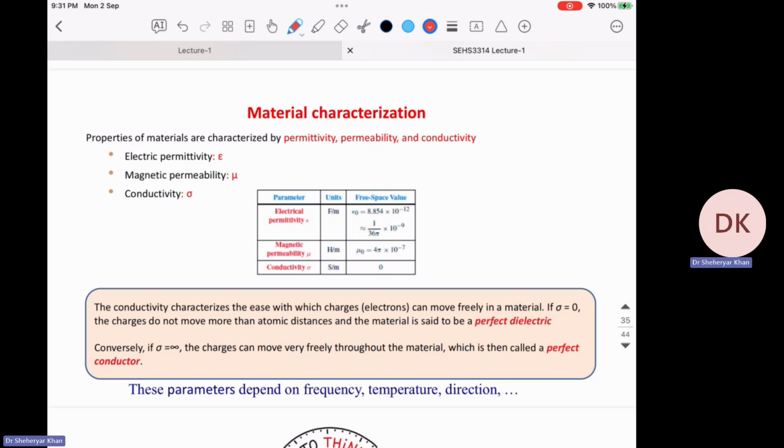You see the DSLR lenses, these contacts, you need to remove many times. You put the lens, remove the lens, put the lens, remove the lens. So there's a slight gold plating, and with the passage of years they do not wear. For better conductivity, we can use silver, but it may work maybe 1 week and then we need to replace it. Copper is also good.